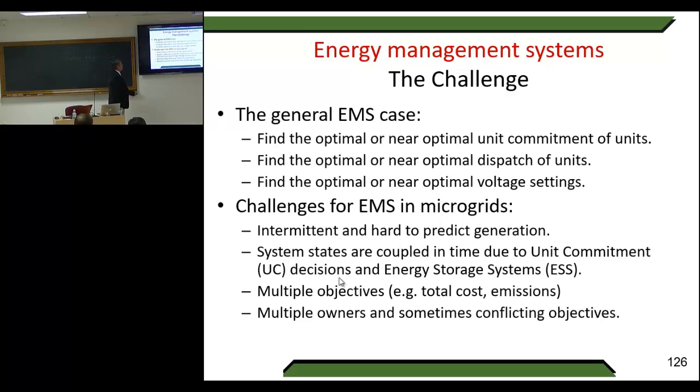The general energy management system case: find the optimal or near optimal unit commitment for the units, find the optimal or near optimal dispatch of the units, find the optimal or near optimal voltage settings. These are the outputs that you expect from an EMS.